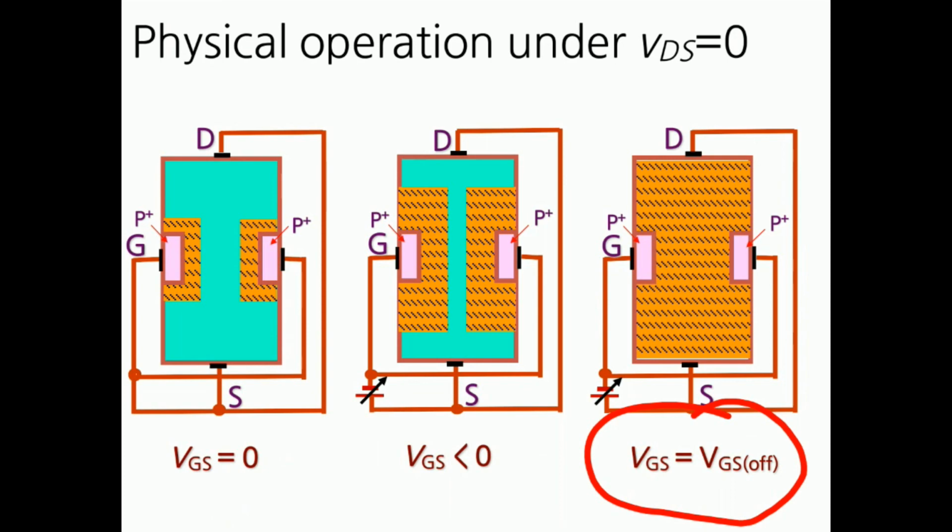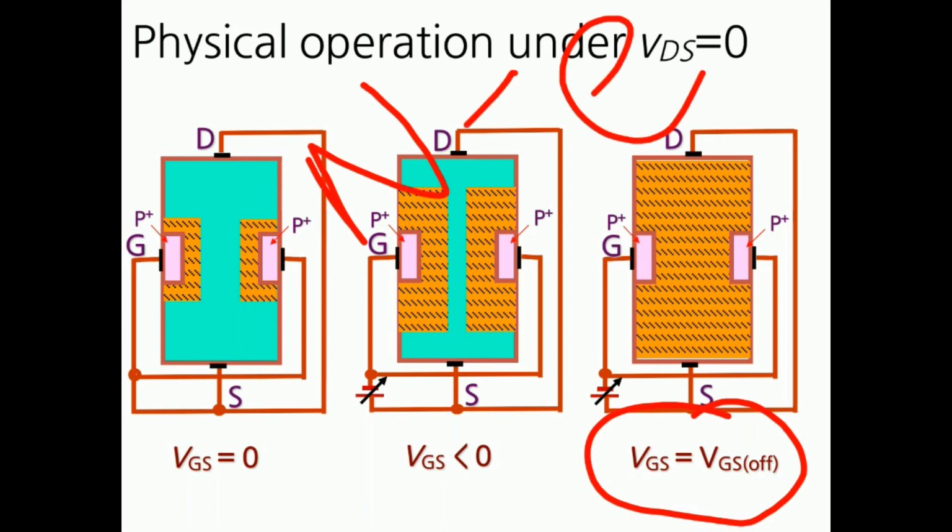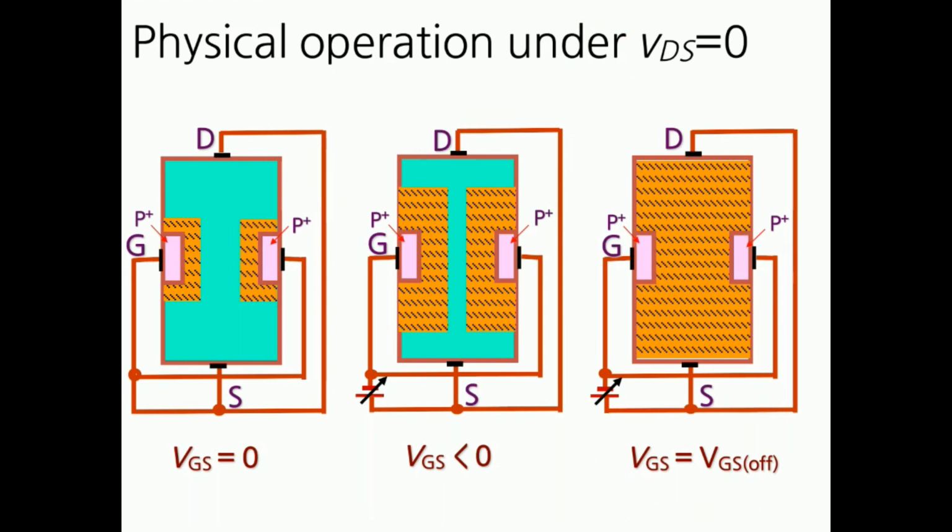And friends, you have to remember the FET is a higher version of BJT, bipolar junction transistor. In BJT, both hole and electron are required to flow the current. Here only one, either hole or electron. If our FET is N channel, then only electron participates in the current. If our FET is P channel, then only hole is required to flow the current between drain to source. So this one is about the FET.